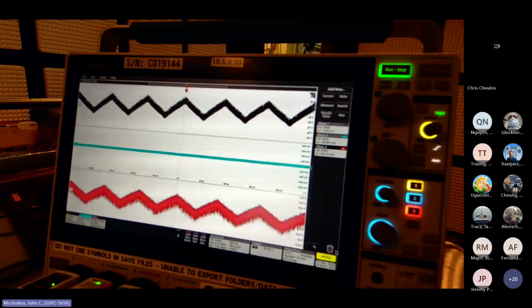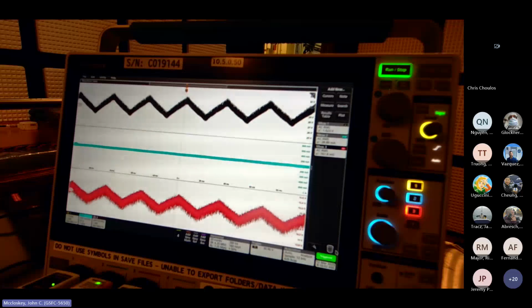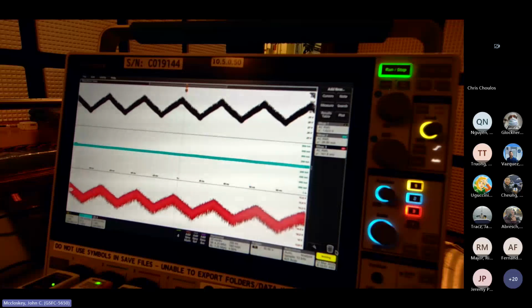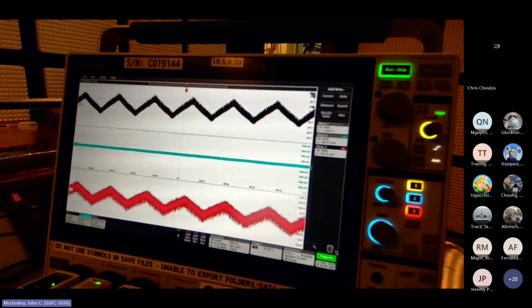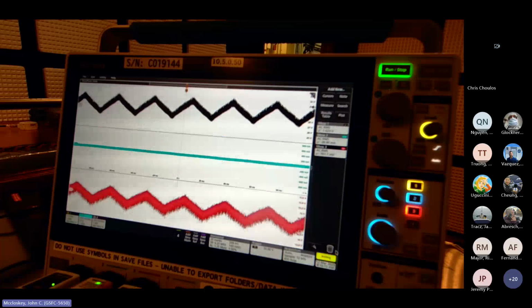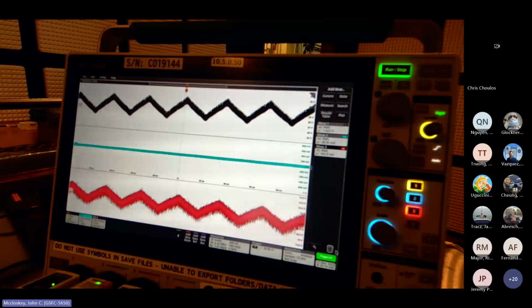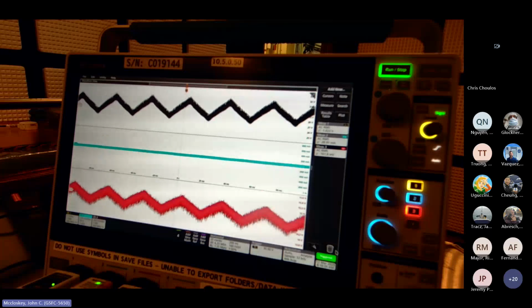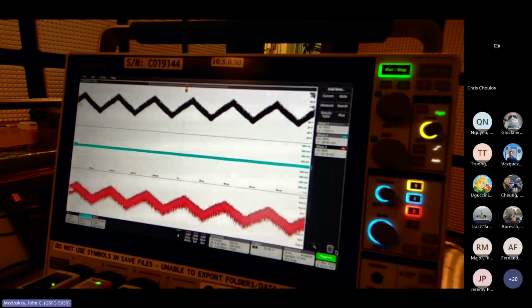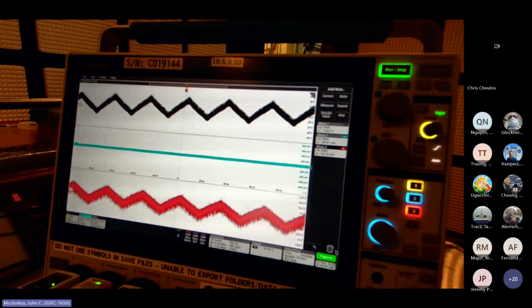But if you actively include the measured current as part of your control loop, and for a 1 volt RMS limit you set a 4 amp RMS current limit, and if you hit 4 amps before you get to a volt, you stop, then that's great, and you don't need to do the pre-calibration step in that case.